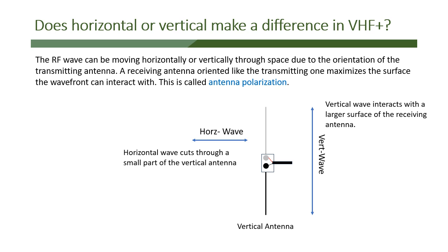So the antennas will be turned horizontally for the receiving and the transmitting antenna. This doesn't make any difference when it comes to HF from the point of view of polarization, because once you bounce through the ionosphere and come back down, you're now elliptically polarized. You're kind of traveling in a circular polarization, and therefore it doesn't matter if you're horizontal or vertical. It's equally not as efficient. There's nothing you can do about that.